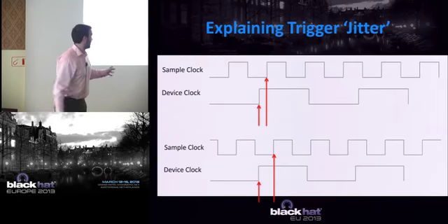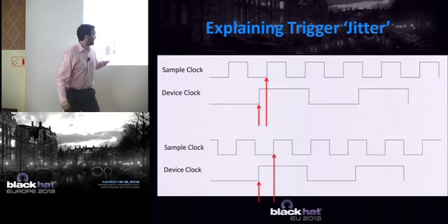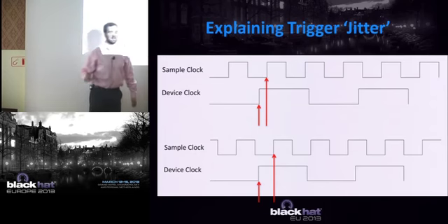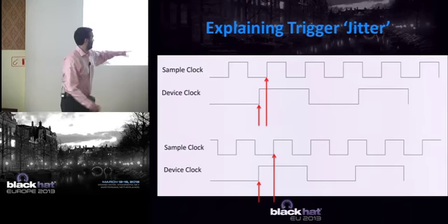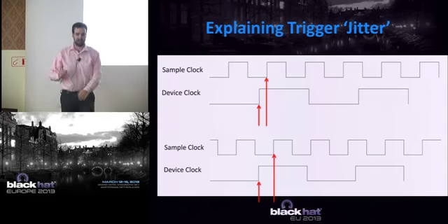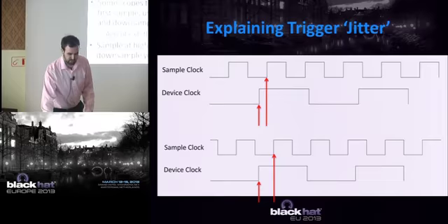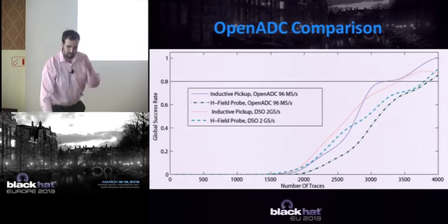Or if you do have a high-speed scope, sample at the highest possible rate, and you can actually downsample if you want to have less data to deal with, but you'll help reduce this problem by sampling at the highest possible rate, even if you don't store at that rate.